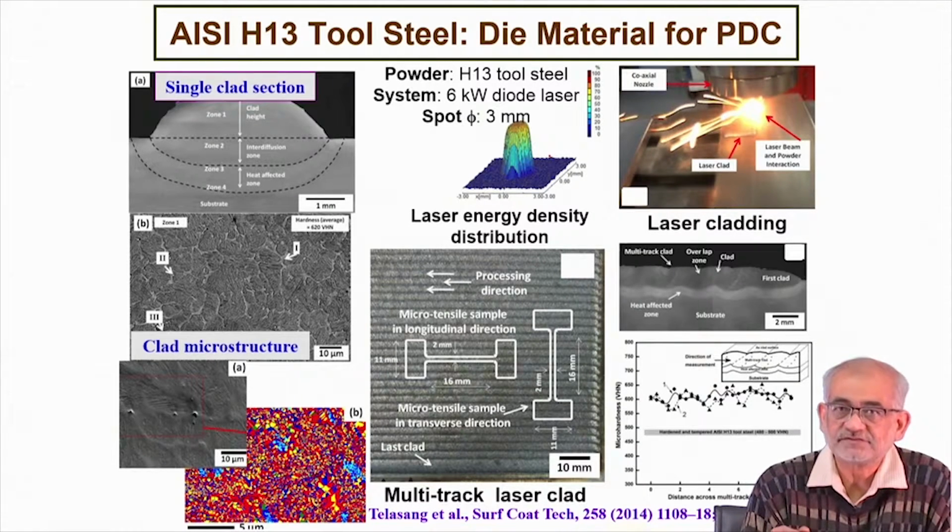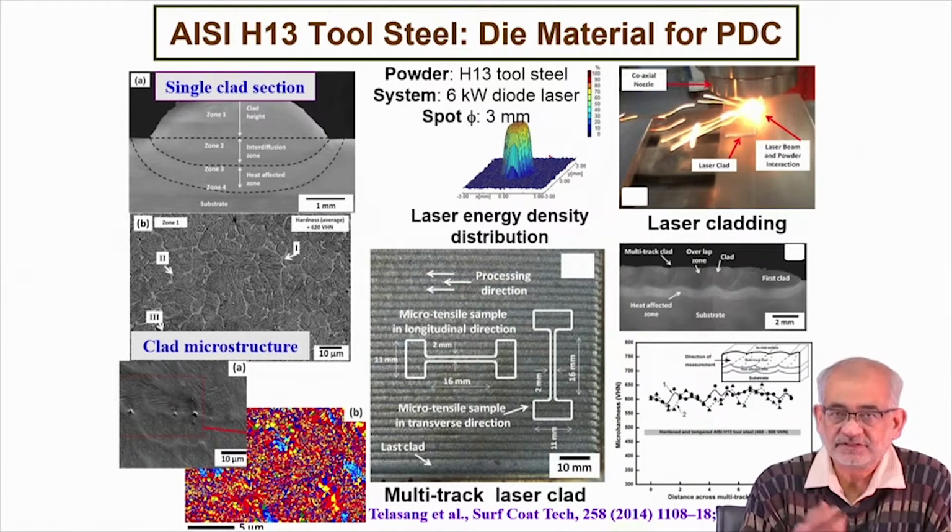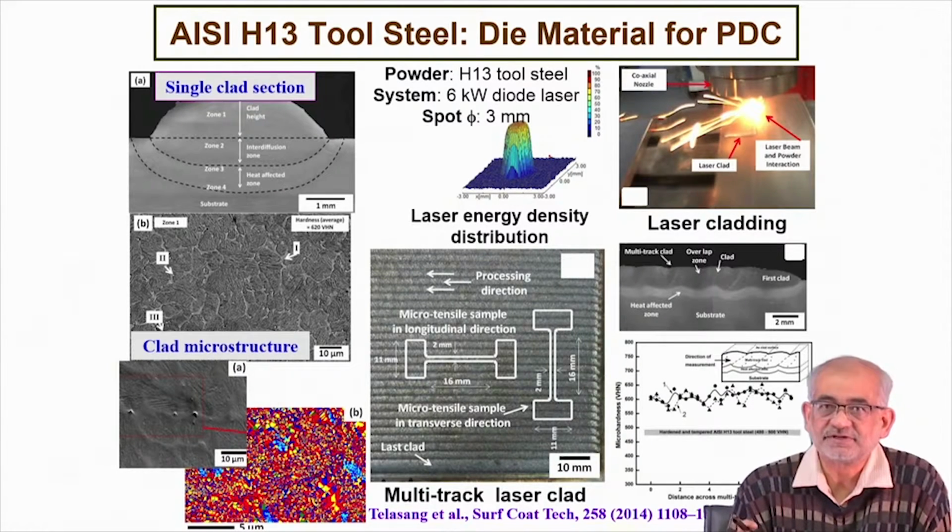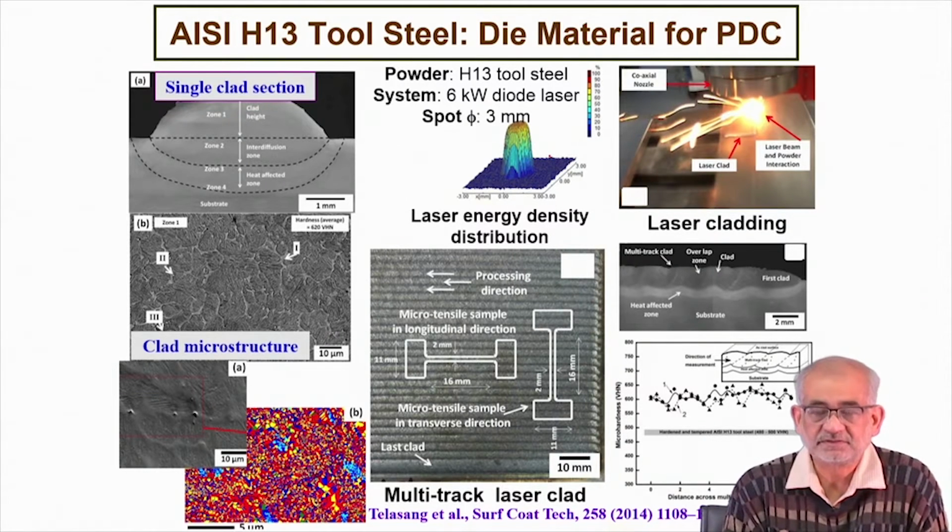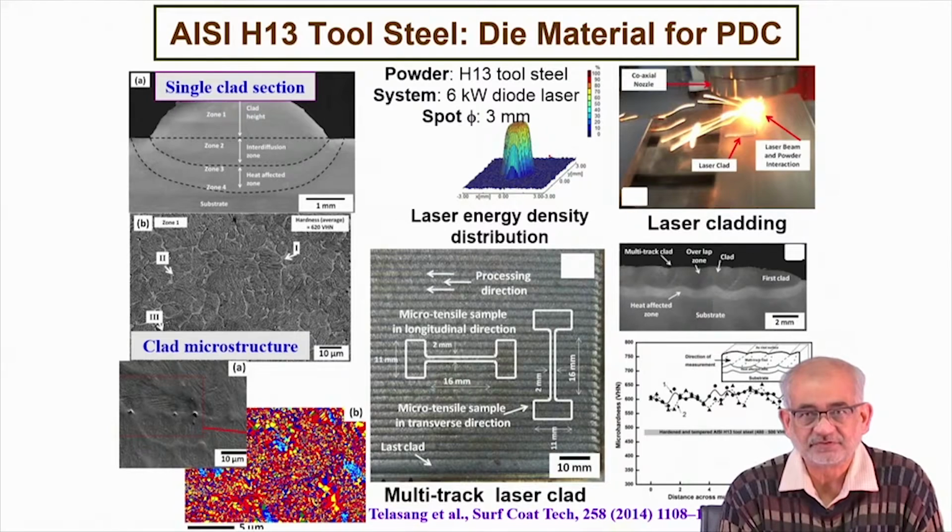The manufacturer always would like to retain and reuse it as far as possible. That is when you go for a reclamation or repair job. We did discuss in the earlier sections something called weld overlay, where you use a welding torch and a filler metal to create an overlay on top of the tool or the solid substrate, and then try to restore the dimension you had before.